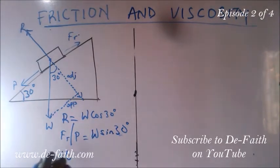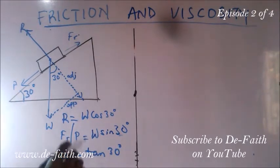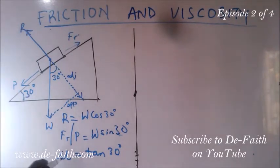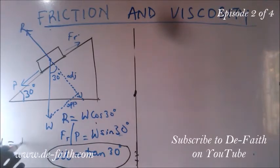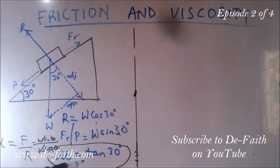The coefficient of static friction is equal to tan 30 degree. That is, depending on the angle you are giving here. So if the angle you're giving here is 60 degree, the coefficient of static friction will be equal to tan 60 degree. And this particular conclusion was derived from this equation. You know, when you have that coefficient of static friction is equal to F over R, where F is your friction, so when you make W sin theta over W cos theta, you end up having sin theta divided by cos theta. That will give you your tan theta. So that's how it was derived.